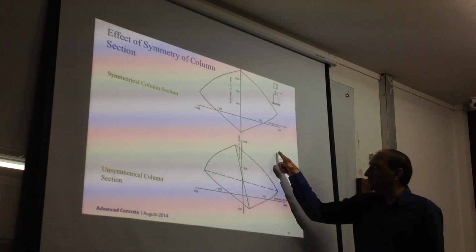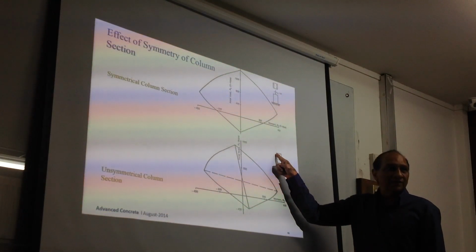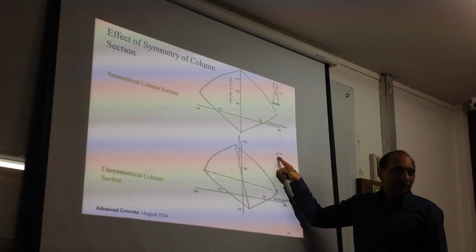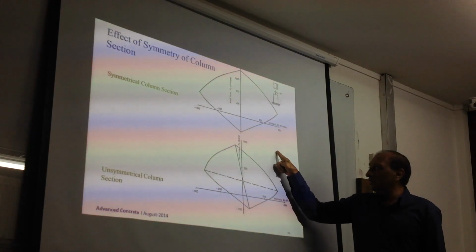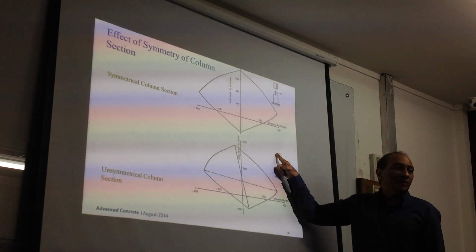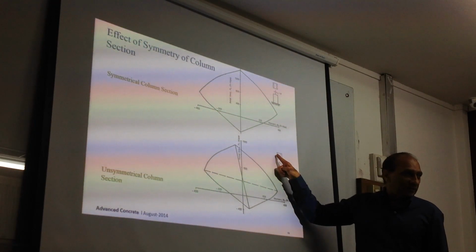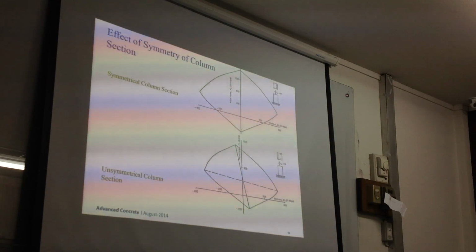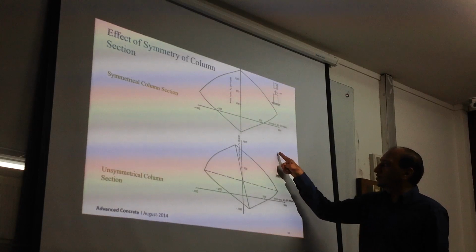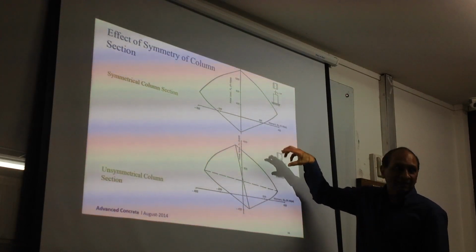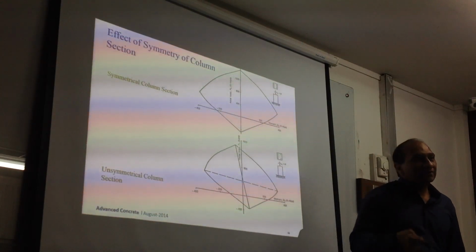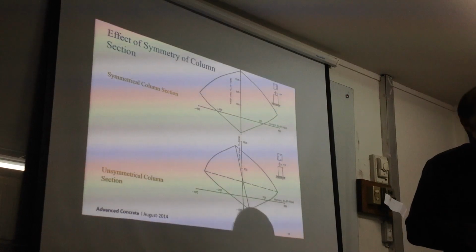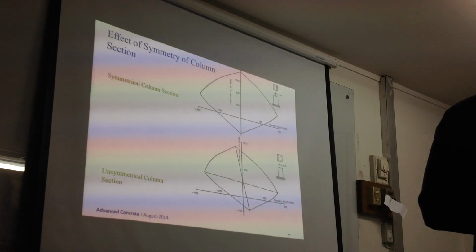That you take the rebar and convert, because they are 2 different materials, so they are not the same. So we convert the rebar, we multiply it by the modular ratio. You remember modular ratio? The ratio between the modulus of elasticity of steel and concrete. We multiply the area by modular ratio, we put a big area here, then we recalculate the section geometric centroid.